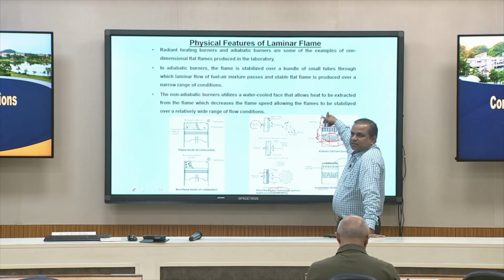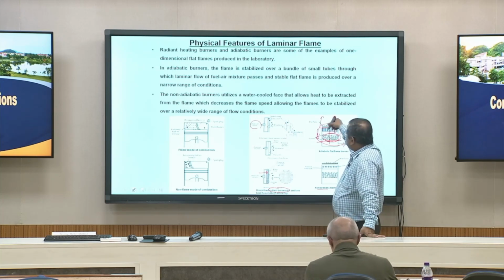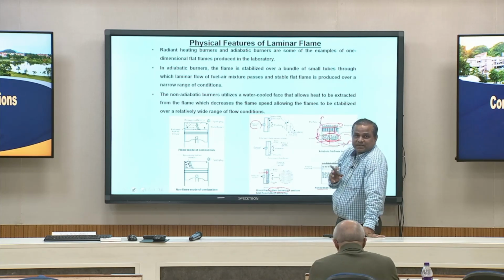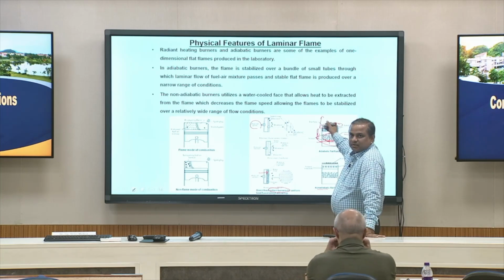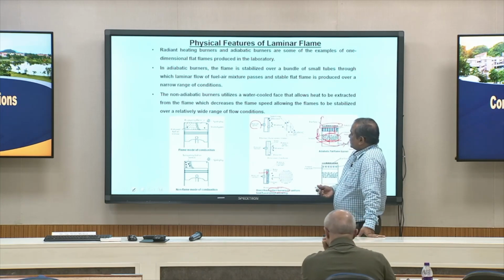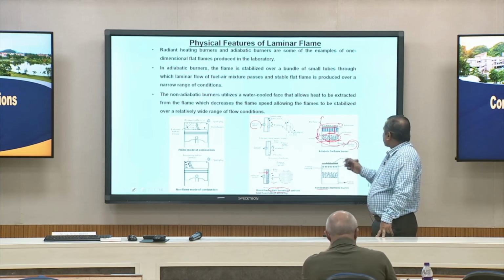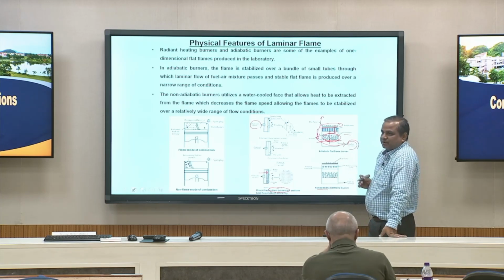They cannot allow the flame to enter, and once the flame tries to enter, it cannot sustain by itself because the bore diameters or sizes are not favorable for it. So that way the flame is killed at this stage itself. Any explosion needs to be avoided, so we require that flashbacks do not happen.